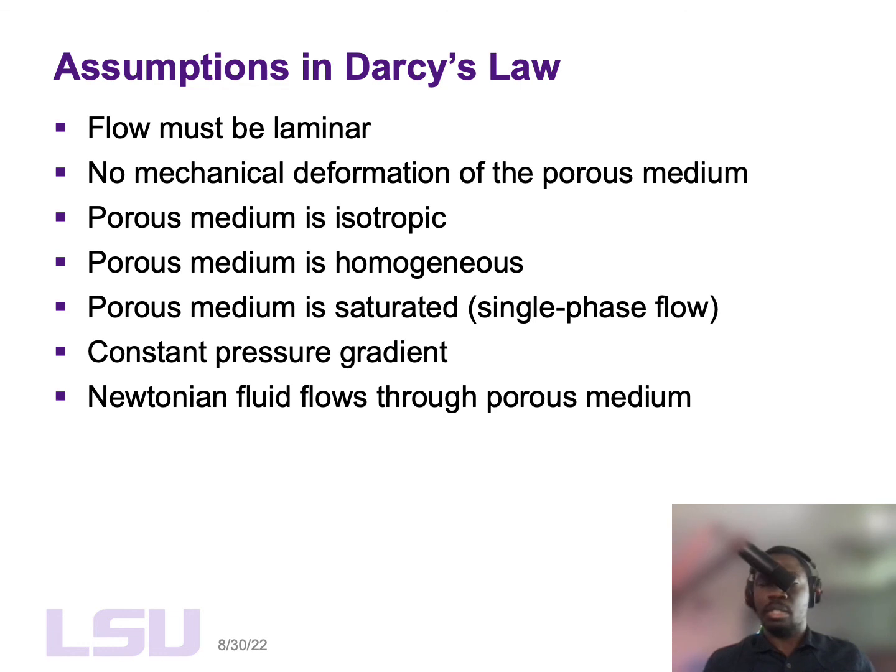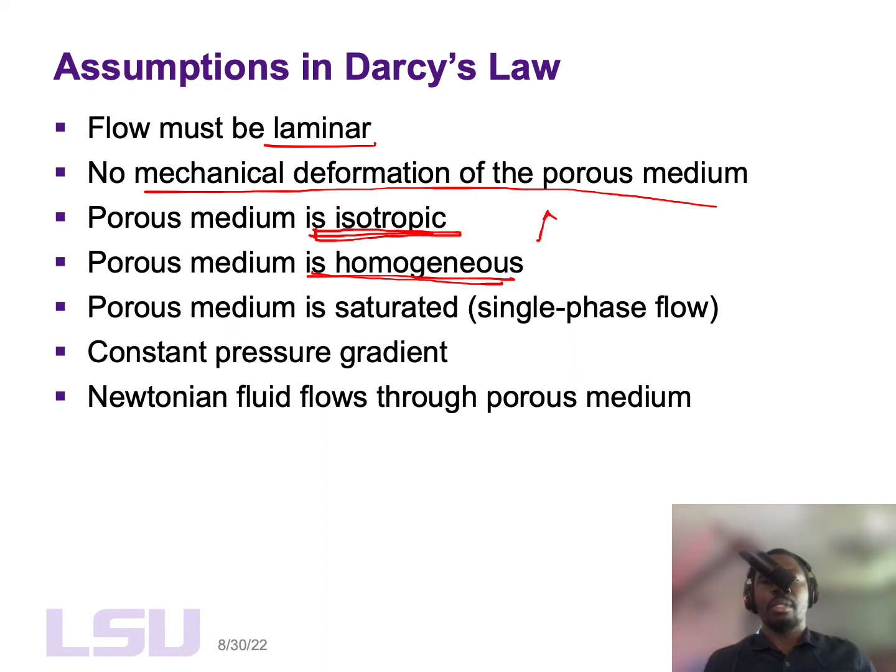These are some of the assumptions in Darcy's law. It assumes laminar flow. It assumes no mechanical deformation of the porous medium, so no geomechanics. It assumes the porous medium is homogeneous and isotropic, but you will see it can easily be extended for the anisotropic case, right, where the permeability could be different in different directions.